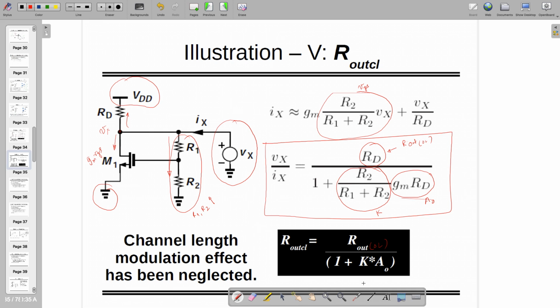In the case of input resistance, it was getting multiplied by 1 plus Ka0 to support the fact that I need more and more resistance. Similarly, I need smaller and smaller output resistance, so in that case it's getting divided by 1 plus Ka0. So you have to make K a0, the loop gain, as large as possible, so that your 3 dB bandwidth is extended properly, your closed loop gain is desensitized, and you are having more and more accuracy. You can have the input and output resistance improved in terms of the loop gain. If you know what kind of configuration you are using, voltage or current, like VCVS or VCCS or CCVS or CCCS, accordingly the resistances will be multiplied or divided by the loop gain, which is 1 plus Ka0, and you can write down the answers directly.